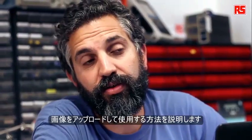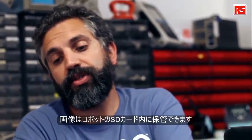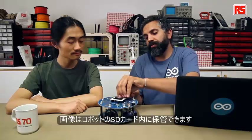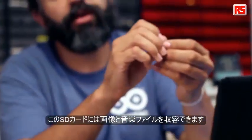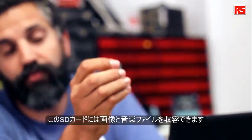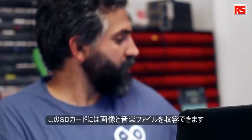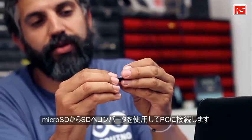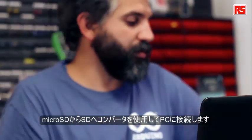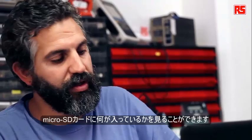For our next example, we're going to see how to upload and use images inside the Arduino robot. You can store images inside the SD card on the robot. This SD card can carry different images as well as sound files like the one we just were experimenting with. We need to connect to the computer, so I use the converter from micro SD to SD, plug it into my laptop, and then I can navigate through the folder to see what comes on the micro SD card.